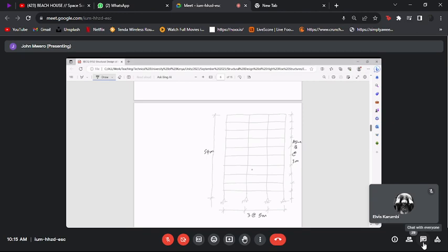From what we discussed in the other unit, we did say, for example, if this building was in Nairobi, then the site is in Nairobi, on the outskirts, not the city center. Then the basic wind speed, and we'll open this standard shortly, is 28 meters per second.